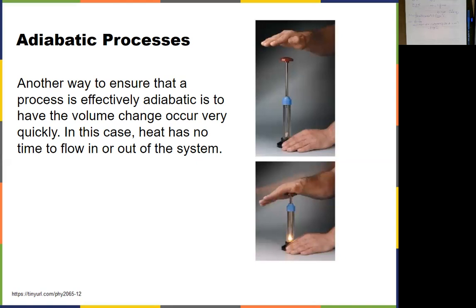All right. So in that process, you are doing the work to the gas system that's in the piston, right? So you are doing the work there. According to the first law, ΔE equals Q minus W. You are doing the work to the gas system, so your W is negative. So then in that sense, if you are doing this so quickly, there's no time for heat transfer. So this is 0 minus a negative work. So then ΔE is increased, okay?